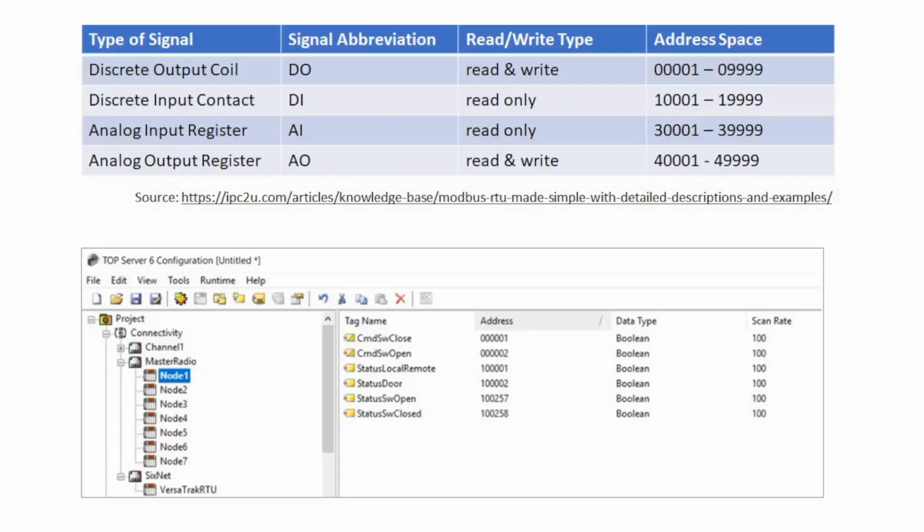For viewers who are unfamiliar with Modbus protocol, here's a basic description of its communication and addressing scheme. In Modbus, a single master unit, sometimes called a client, polls a number of field devices, called slave or server units. Polling means that the master unit updates its memory for field device statuses and issues commands to the field devices by communicating with each device one at a time in an ordered fashion. The field device will only transmit information when it responds to a master's poll transmission.